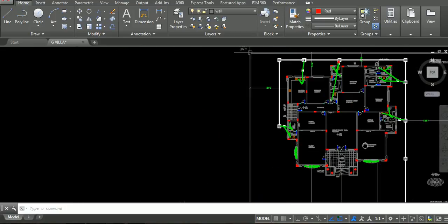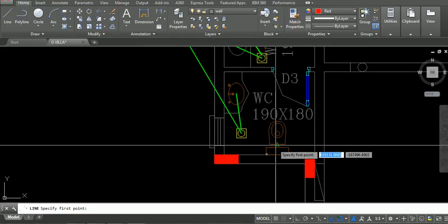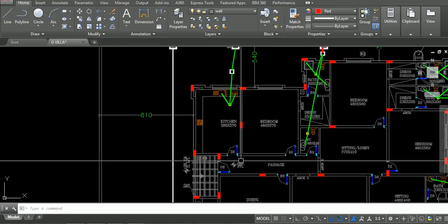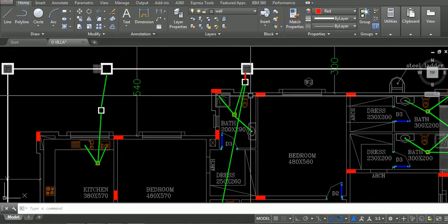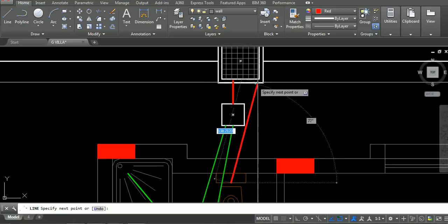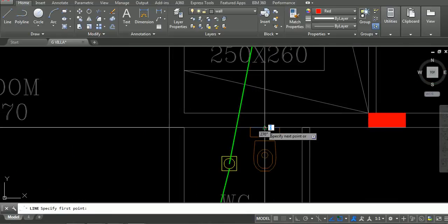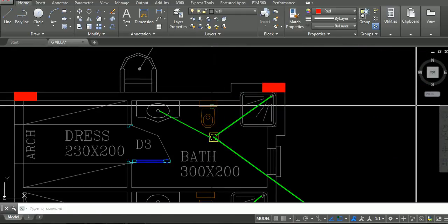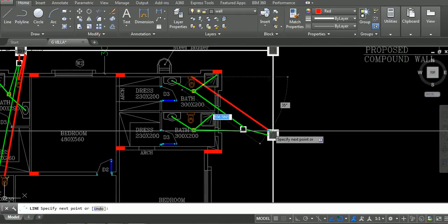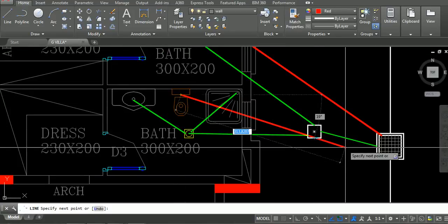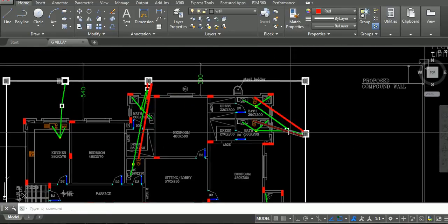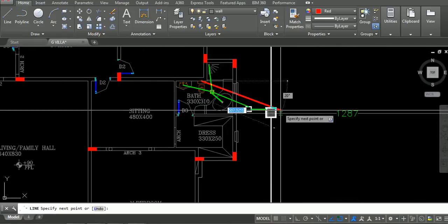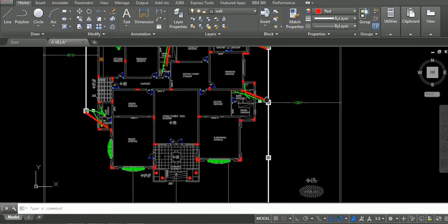Now after that, let's connect the sewage water directly to the manholes, because there is no need for a gully trap for it. Directly connect it with the red line. I do it usually with the manhole directly. Also here it's going to cause a problem. I'm going to explain later what I'm going to do to solve this problem. Here you'll start seeing that lines start crossing each other. It's just random also, but everything will be cleared later, don't worry about that.